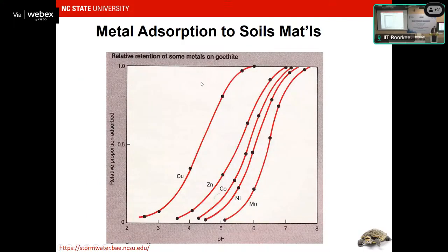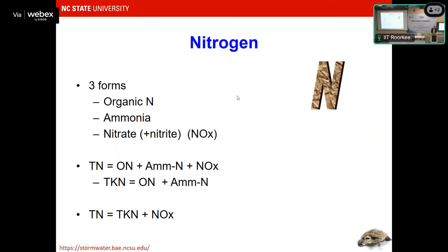That's how inorganic adsorption works. By the way, pH matters. So the more acidic it is, the harder it is. Even though aluminum or iron loves dancing with zinc, the more acidic it gets, the less it wants to hold on to zinc. All right. So you want a nice neutral situation, so that the dance goes on forever. All right. Now let's move on to biological transformation.